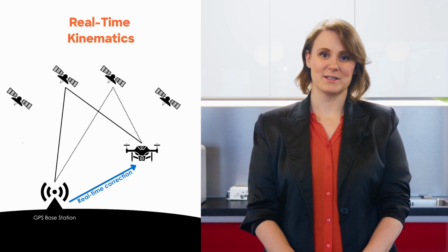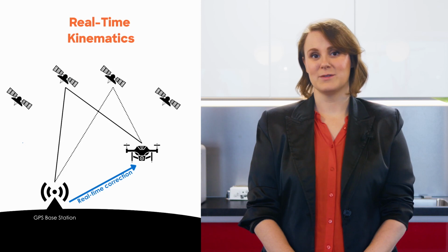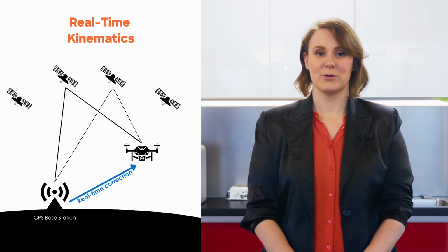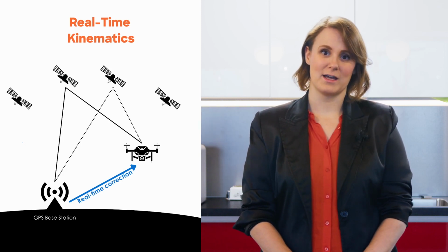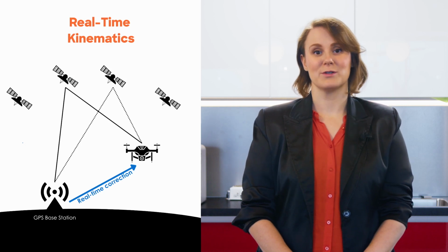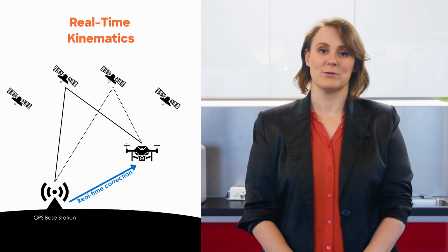Another way is to use a drone that has RTK. RTK stands for real-time kinematics, and practically it means that the photos that the drone collects are equipped with higher precision and not only rely on GPS. When each photo collected with an RTK drone has high precision, the processing afterwards is smoother and easier and doesn't require ground control points.